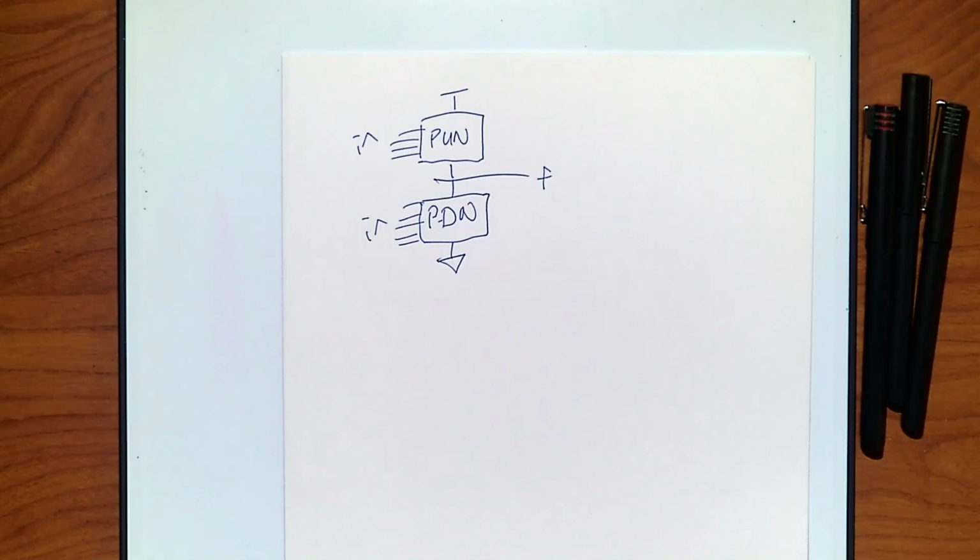There are other ones that can change and might only have a value that's good for a period of time. When you change the input, there's a short period of time for it to update because there's some dynamics to switch to the new values. But once that switch is done, it stays static. If you leave it there for 5 minutes, it'll still be the same value. That is not going to be true for all types of logic we do. In some cases, there is a short period of time that the signal is valid for, and then it becomes invalid. And it turns out that those ones are faster.